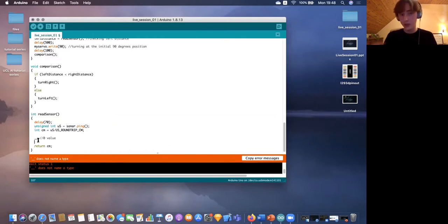So we have to think about this case, since if the obstacle is 5 meters apart, our robot should go forward, but if it returns the 0 value, which is illogical, it is going to stop and check distances to the left and right, which is not logical as the nearest object is 5 meters apart.